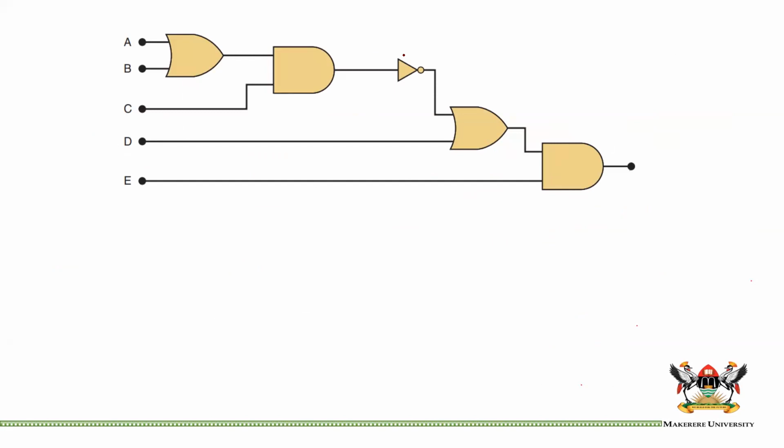So you can see that this is a rather complicated circuit, but it is really not once you have learned this stuff. So let us do it together. We start from this side. We can start with this first gate. So we have inputs A, B, C, D, E. We have 5 inputs, and you can see the inputs go into different gates. This is an OR gate, so here we have A or B. And this term is ANDed with C because that's an AND term.